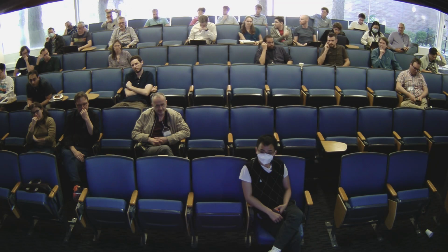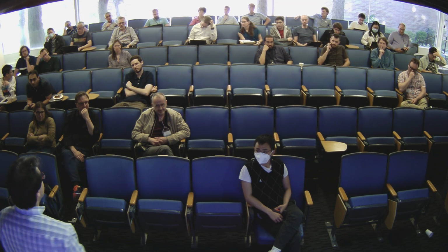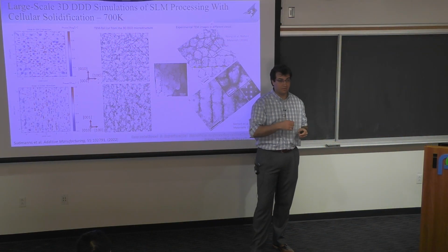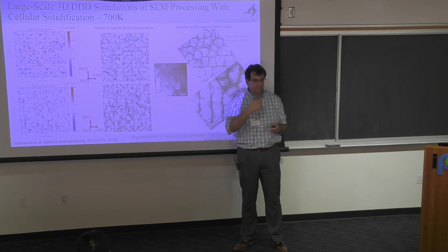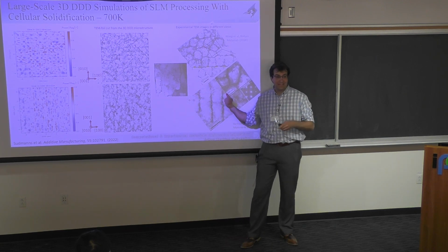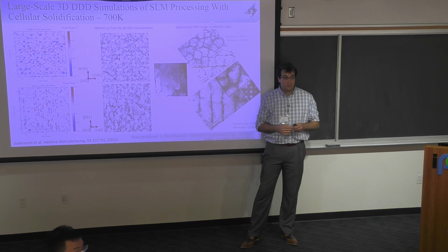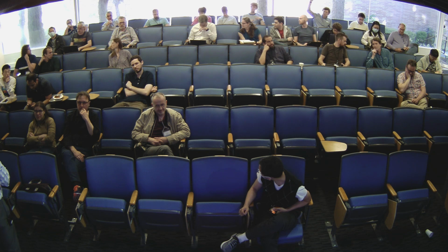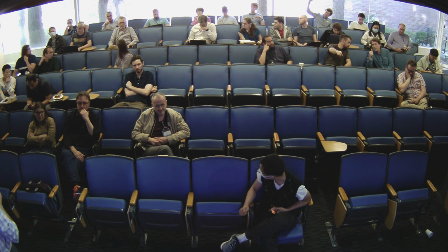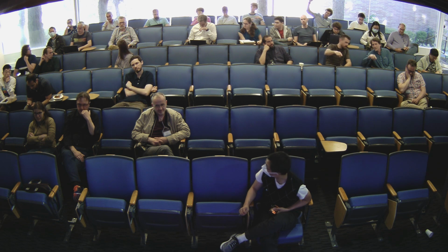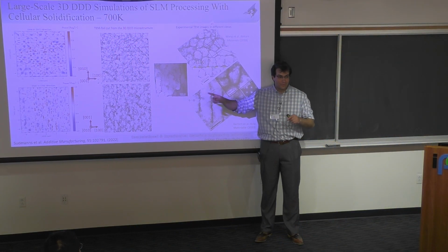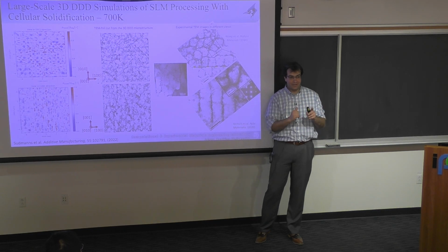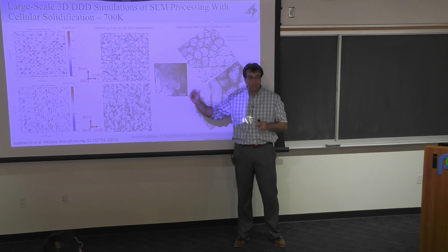So what is the linear size of your sample? The size of the entire simulation cell is 10 by 10 by 10 microns. The foils are 10 by 10 by 1 that are extracted out of the larger simulation volume. And I'll tell you right now, because I don't know if I'm going to get time to. If you reduce your length scale to 1 micron, would it sacrifice something? What I'm going to tell you is the 10 by 10 by 10 is actually wrong. It was interesting because we knew this later on, that the simulation cell size actually really matters.